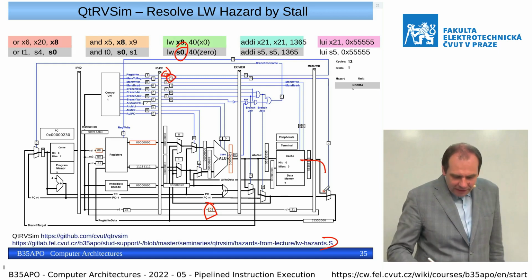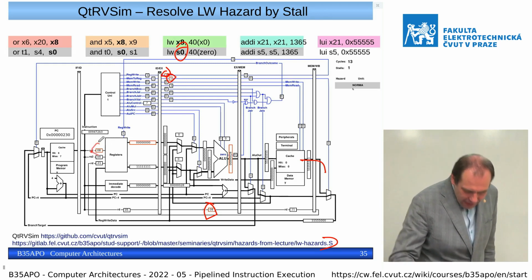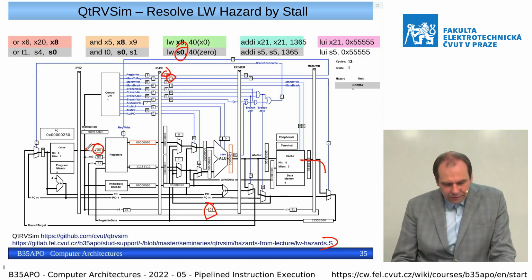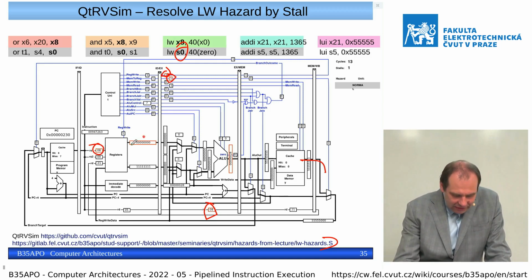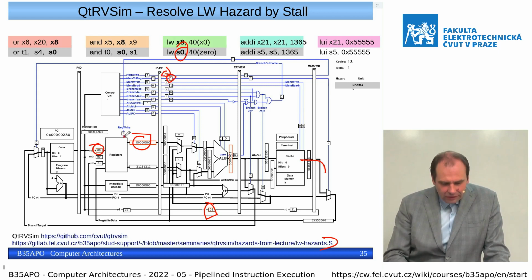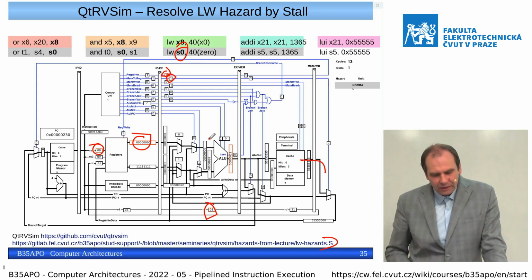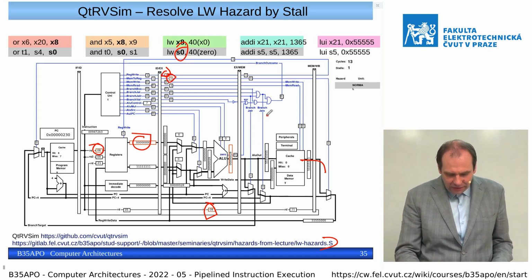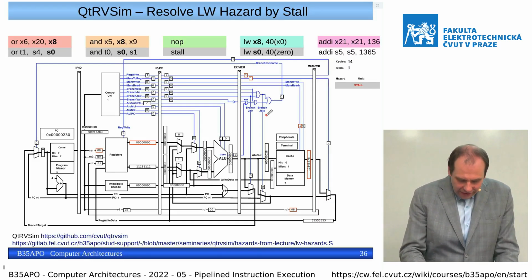So in this specific case, if there is a match with the read register from the register file, then we see that there is an incorrect value, and we know that we cannot use forwarding. So in this specific case, we provide a one stall cycle.